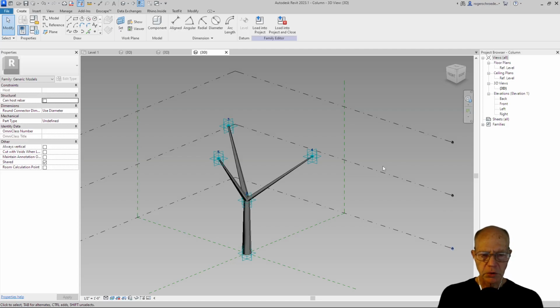You're looking at the space frame, or excuse me, the adaptive column that we're going to build and use to support our space frame. And you'll notice I've created 3 levels for it. That midpoint level that we did will correspond to point 2 here that's in the center of the screen. So we can adjust kind of like the midpoint of our adaptive column.